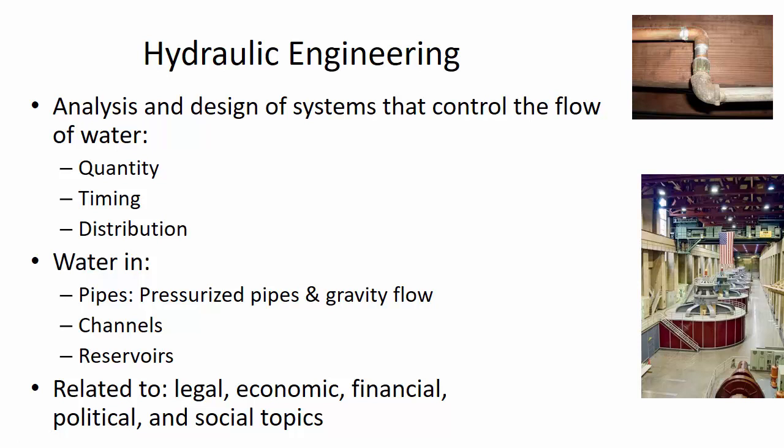And that's one of the cool things about our design project, is that you'll very easily design a network that does the job, that delivers the quantity of water and the pressure that's needed. But then you'll start chipping away at optimization, where in this pipe network you'll be making one pipe a little smaller and then another one a little smaller, and you'll just keep pushing it more and more until maybe the system starts to fail, where the pressure's too low, where you've gone too far and made the pipes too small. So you'll be balancing out performance with cost.